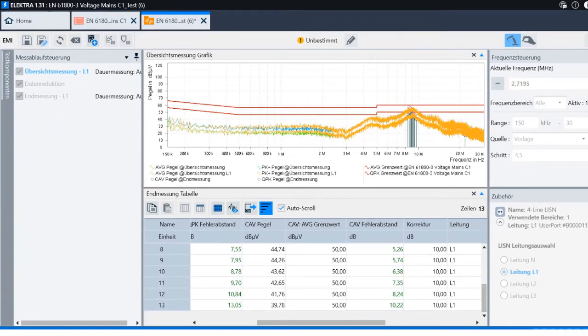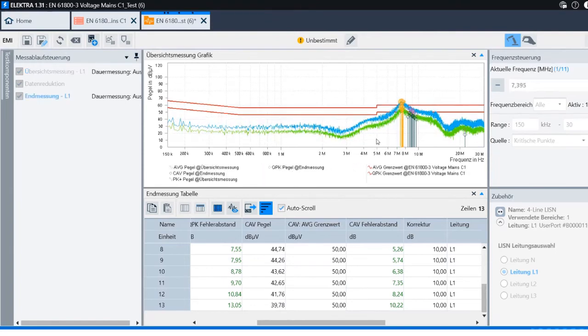This measurement here shows the measurement with the no shield attached. So the shield is still on the cable, but it's not attached on motor side or on the drive side. And then it's even higher in the higher frequency ranges.